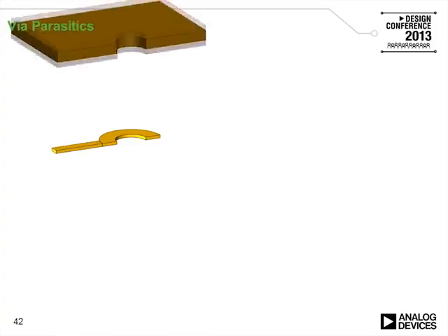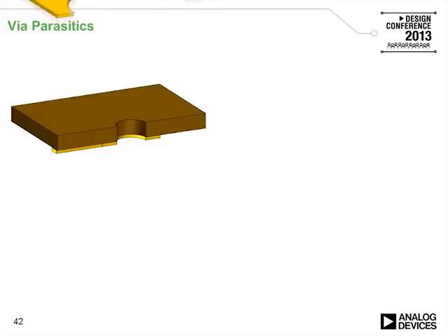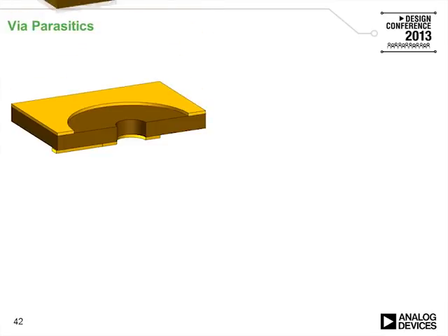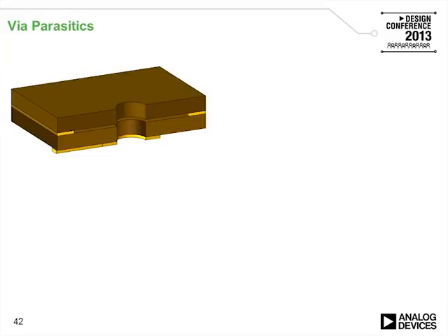Here's half of a via on the bottom. Here we'll attach a conductor. We'll put an insulating layer on top. We'll put an internal plane layer with a low clearance. We'll put another insulating layer. On the top layer, we put the other half of the via, and we make a connection to some circuitry. We'll put the barrel in to make the connection between the top and the bottom layers, and we finally put some solder mask on. This is how the cross-section of a via looks.